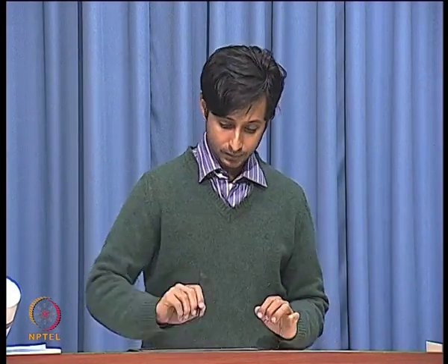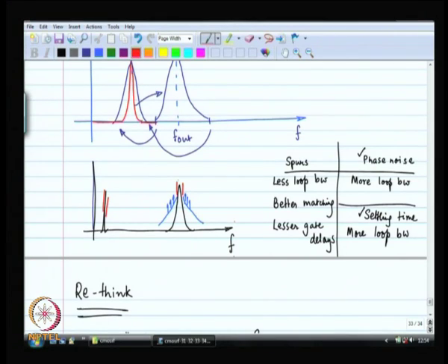I will not have to worry about phase noise right next to my oscillation frequency, right. So, the output of the synthesizer will mimic the reference with a larger bandwidth, 10 times larger bandwidth, and that is a lot as far as I am concerned. That means a lot to me.